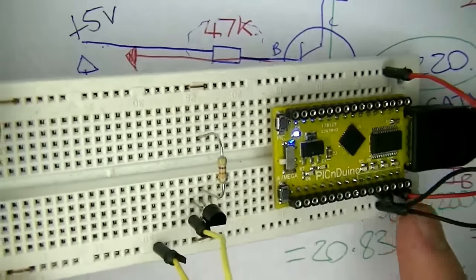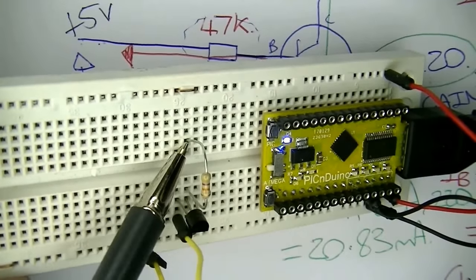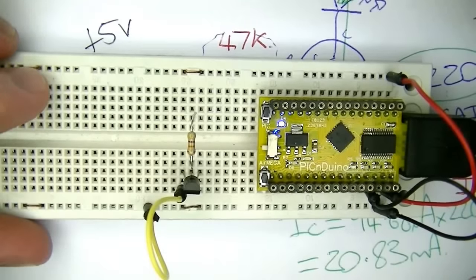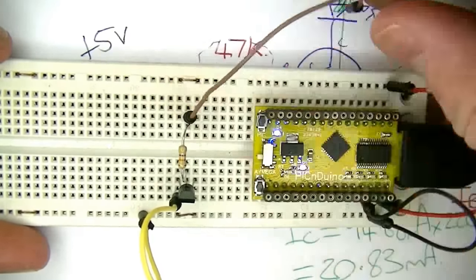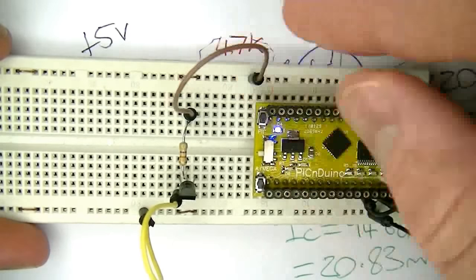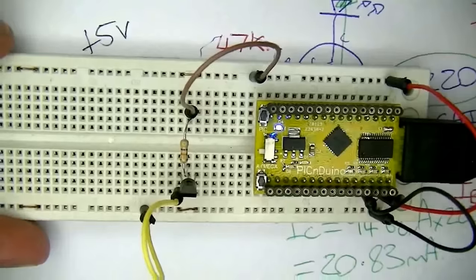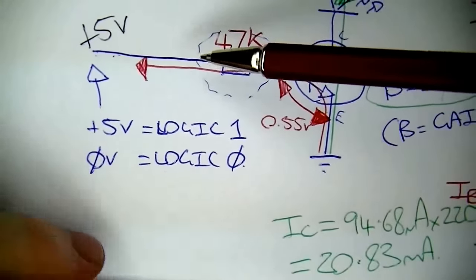So it's connected to the base in the middle there, and then I've just connected to a blank spot here. And then I'll connect a wire from that, I just bumped the camera, to plus 5 volts. This top row here is plus 5 volts. Okay, so that completes the emitter and base circuit.